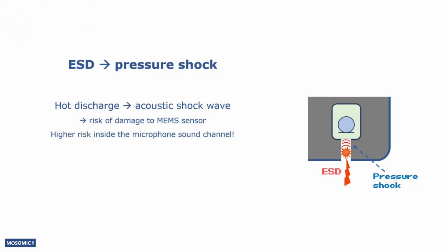In addition to the electrical shock, an ESD spark exposes the microphone sound sensor also to a pressure shock. When the very hot discharge travels through air, it heats the air surrounding it, resulting in an explosive expansion of the air and thereby a pressure shock.